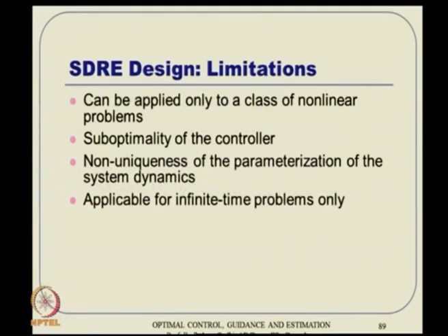And then the entire design is applicable only for infinite time problems, because the Riccati equation has to be solved. It cannot be a dynamic equation, it has to be an algebraic equation. And an algebraic equation demands that tf has to be infinity. So that is applicable only for infinite time problems.